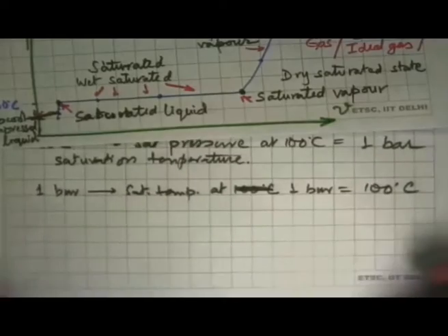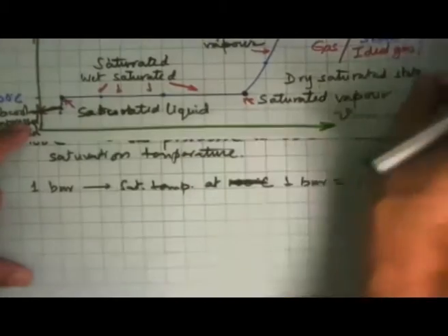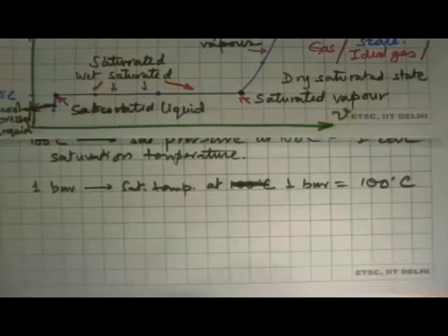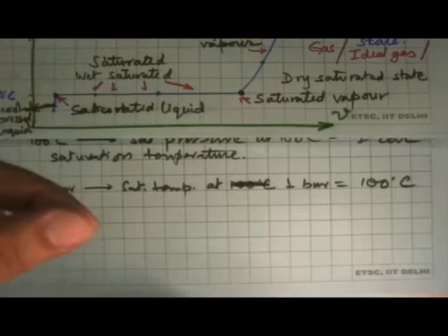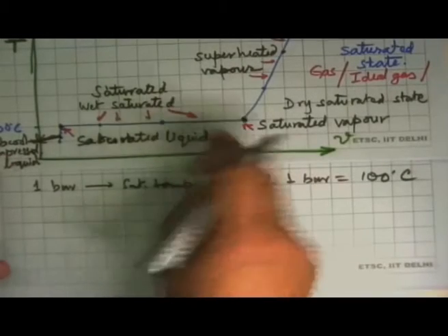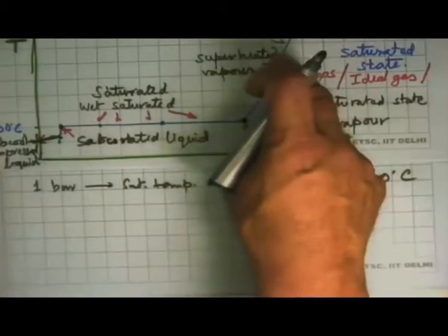And now we say, well, what happens in the other cases? For this, one only needs to go to a table, and these properties are well documented, and you say, look, for this material, this is the pressure, this is the saturation temperature. And the pressure in this case is 1 bar. In a minute we will see what happens if it is 10 bar, 0.1 bar, or if the substance is different, everything will fall in place. What we will define now is, compared to the saturation properties, what can I say about subcooled and superheated states?